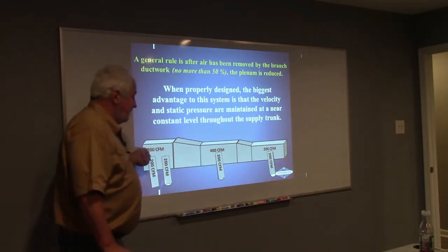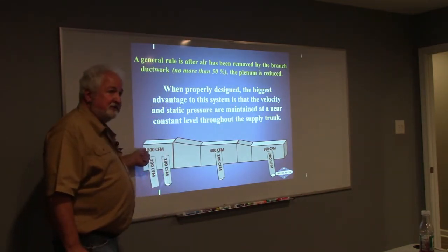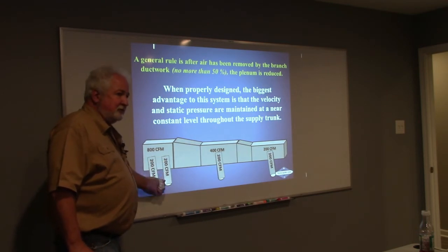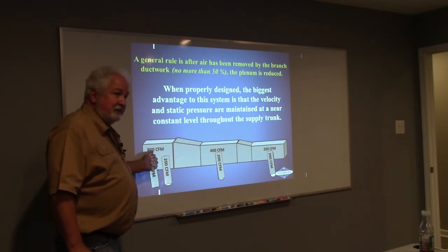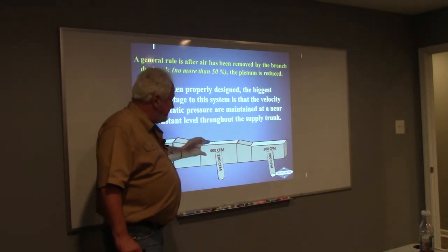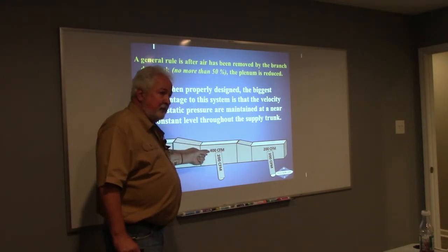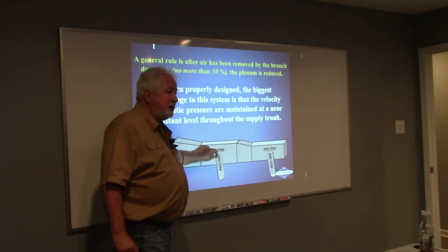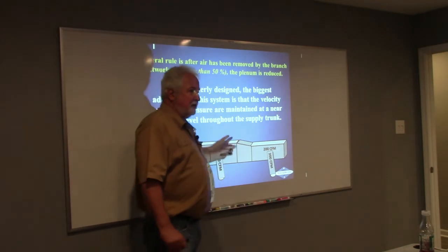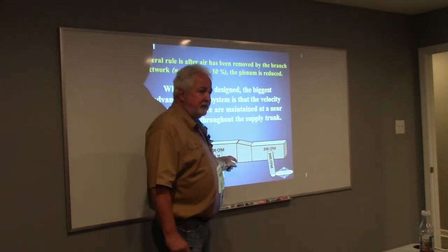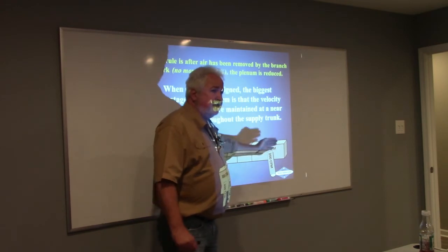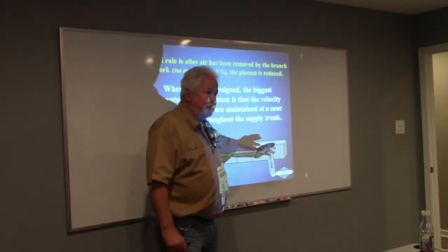So you have 800 CFM. You have a 2-ton system. You move 200 CFM, 400 CFM. Is that half of 800? Good, you transition. Now you're going to size that to 400 CFM. 400 CFM goes out, I drop 200 CFM off. Is that 50%? Good, I'm going to transition. Does that make sense? That way I'm able to keep the static up, and I'm able to keep the velocity up. Everybody with me? Good.